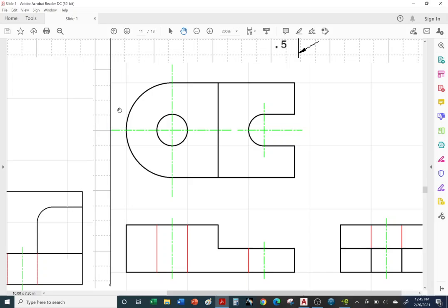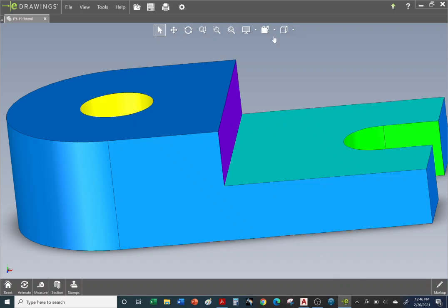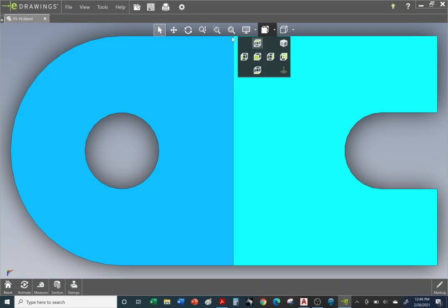Let's go ahead and do the top view. Obviously we have this object line missing. So from this corner, get into the habit of going to all the vertices and projecting. And you also project across. It's already there for the right side view, but we are missing this line. Let me show you from the 3D model, top view. So we are missing this object line, and we need our green center lines. All right, so let's go to AutoCAD.